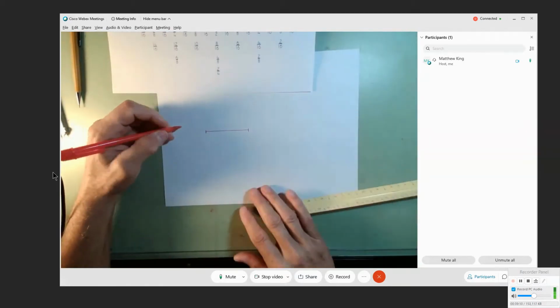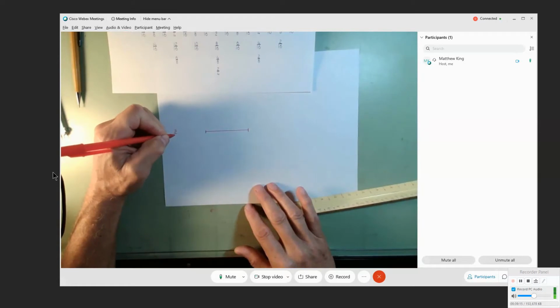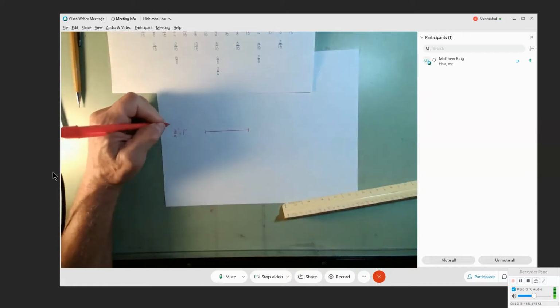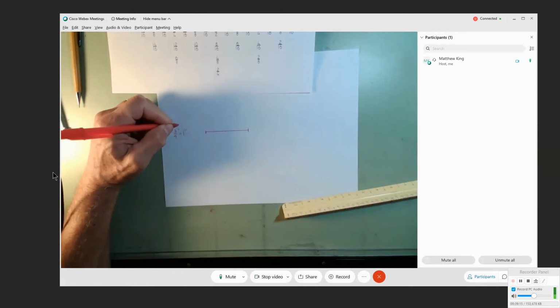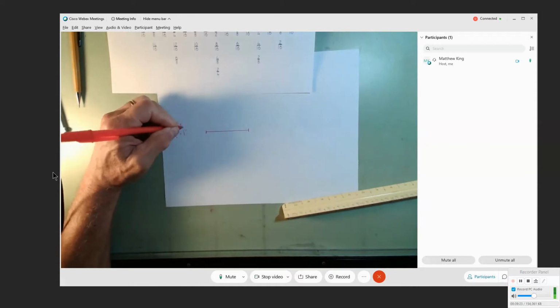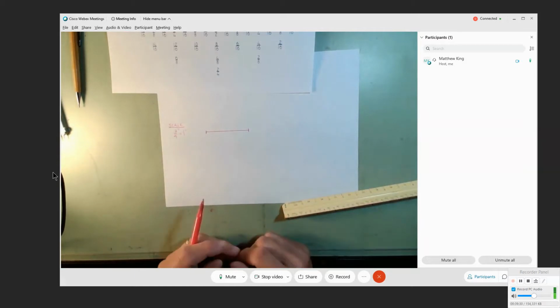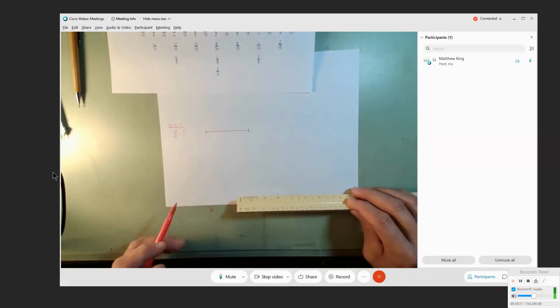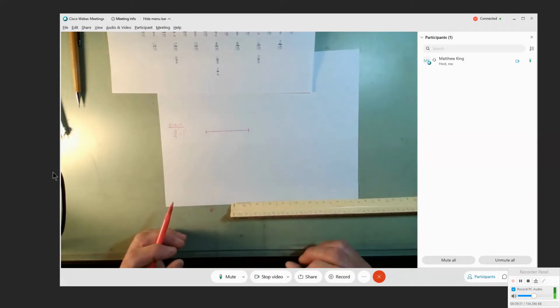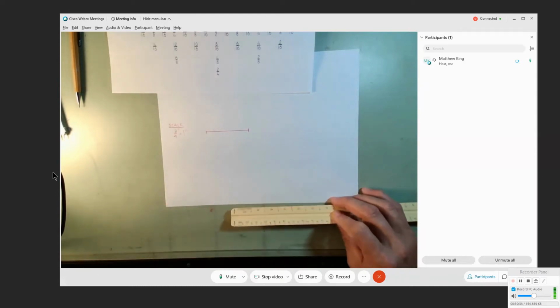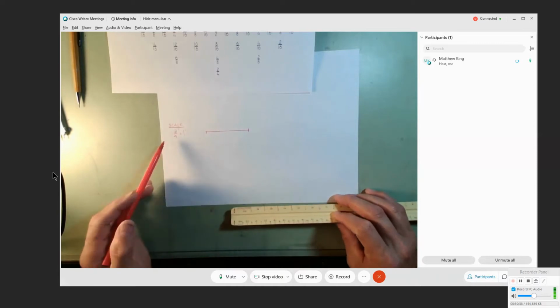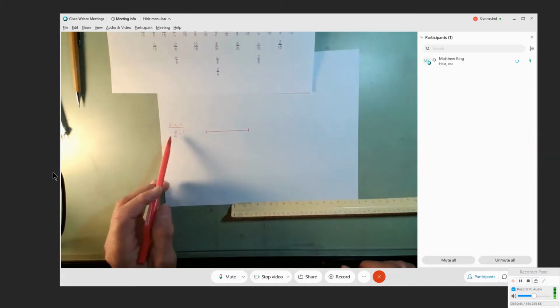So we would have to know that this is 3/4 inches equals 1 inch. That's how we would formally write the scale. So what does that mean to us? When we have our drawings, we have in the title block a category that says scale. The assignment that I gave you last week that's due this week, the scale of that, I told you to just write the word full. Full means 1-to-1 or actual size. Now we're going to start getting more specific.